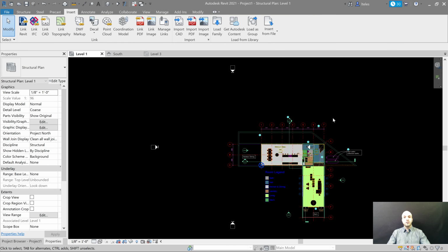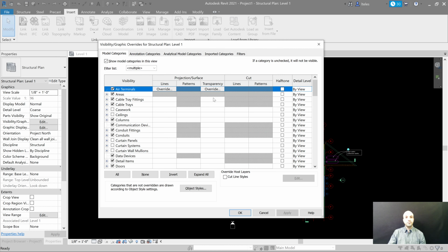All right, so in this case I'm just going to hide. Remember, whenever you use the word on, off, hiding, think of visibility graphics, and every view has its own visibility graphics. I'm going to turn off or hide my elevations. So let's go to VG. We're going to start getting into keyboard shortcuts here. VG. Let's go over to annotation categories, and now let's look for elevations.